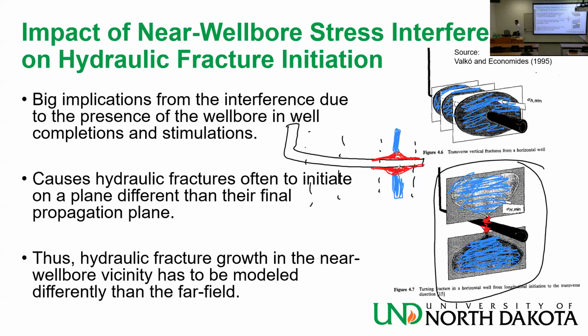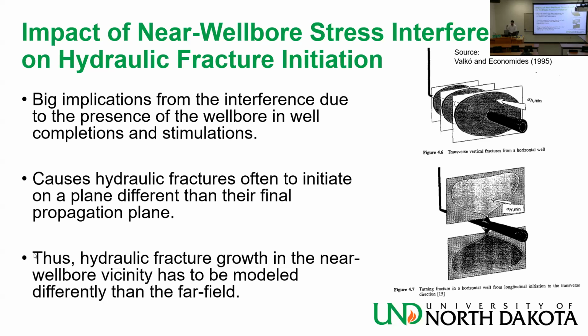If I get these longitudinal components extending beyond the stage, it means I'm getting fracturing fluid going to another stage. So I create inefficiencies. I don't create the fractures that I expect to create here. And then I have a stimulated well that is not producing as much as my model is predicting it to produce. And I have a discrepancy. And then I have to reconcile this discrepancy. And this is what Valko and Economides propose. I get this.